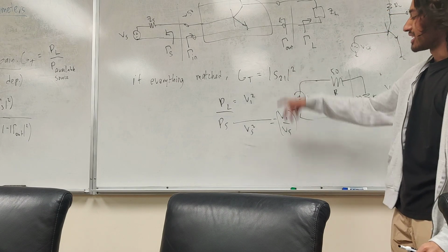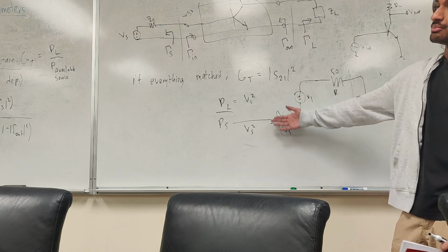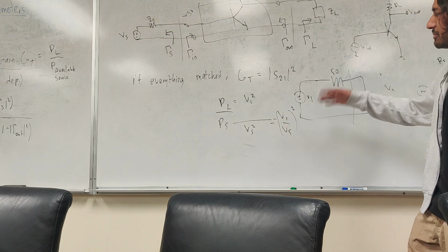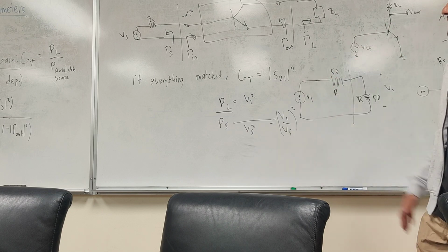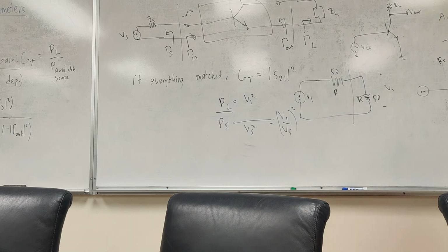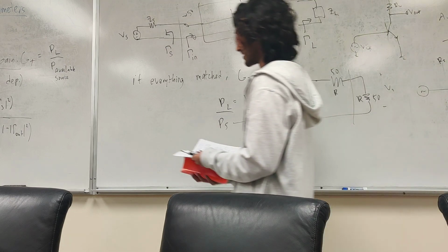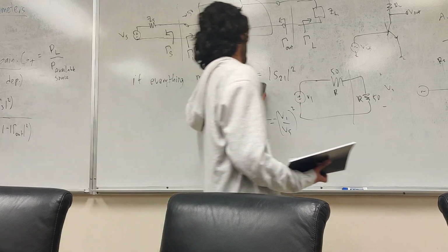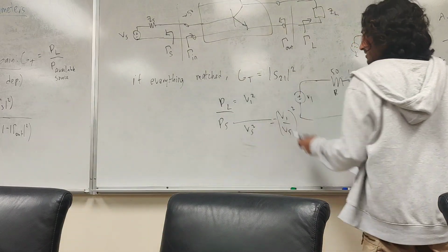Now these numbers may not be exact because we have a reflection. Just for the sake of example, that's how the units work out. In case anyone is confused, because we go from dB to voltage to power, and it's not explicit which one you use when you use S parameters. Through experience you'll realize what they're talking about. There's no exact rule, it's just convention. It's very annoying. But hopefully this explains it to you, because I never had anyone explain that to me.